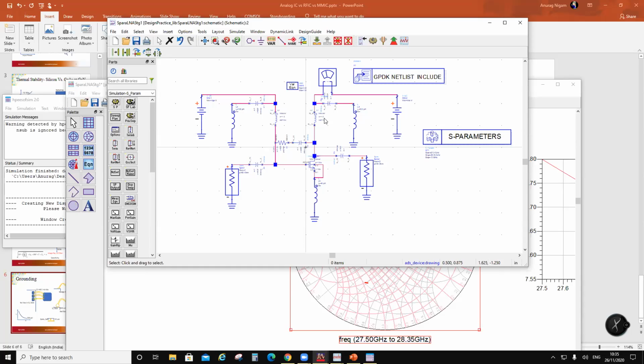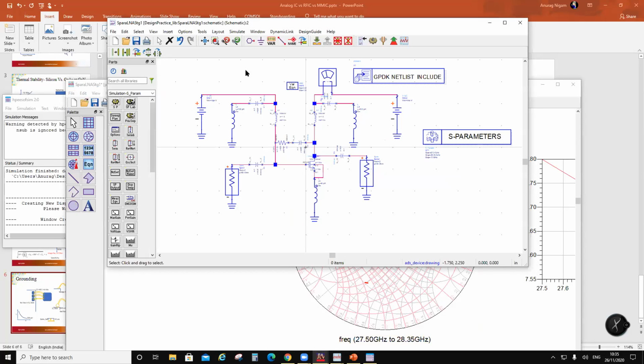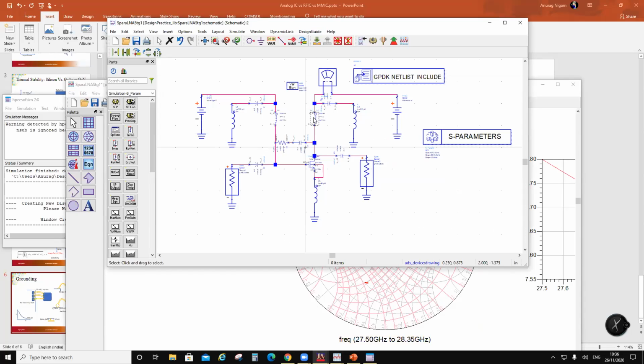Okay, next thing is people will put a tank circuit here, a capacitor in series with an inductor. Now the problem with that is it is going to roll you fast to the open circuit, but then it is going to roll over. So the bandwidth you are working with is going to be reduced. So if you are doing broadband amplifiers, you cannot put a tank circuit here. If you are doing a narrowband amplifier, you can put a tank circuit here and a much smaller inductor so that you can create an open circuit here. If you want to do a broadband, use a large inductor. And if you don't want to use a decoupling here, this is a part of matching, then you have to create a very good short here.